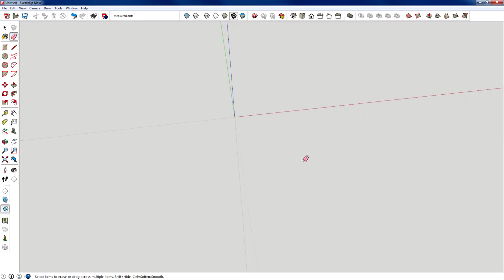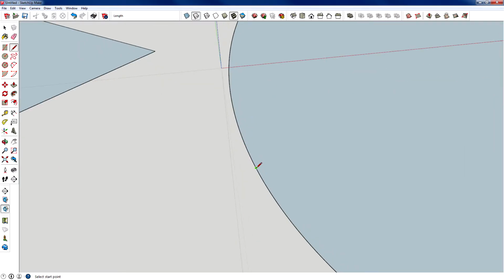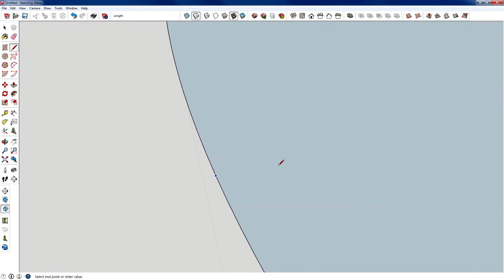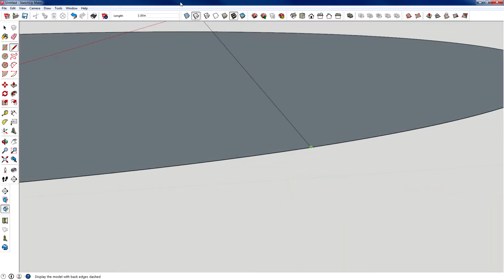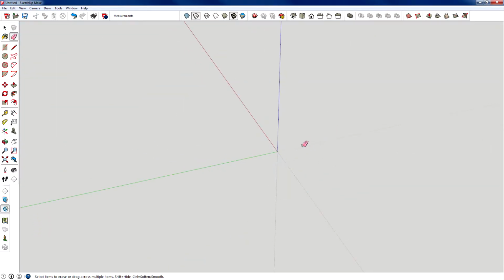You can change the settings for this. When you click on it, the number is up here in my case. We could change this to a minimum of 3, which gives you a triangle. Makes sense. You can also change it to make something like 300, which, although it looks like a circle, is still a polygon. You can select the line tool with the default key L, and the erase tool with default key E. You can also select all with Control A and delete.